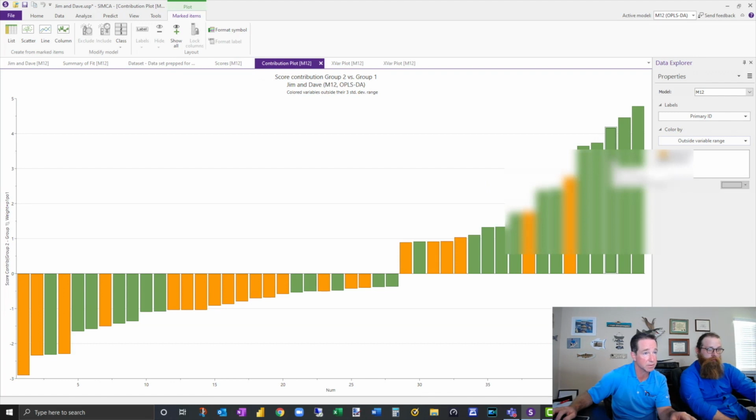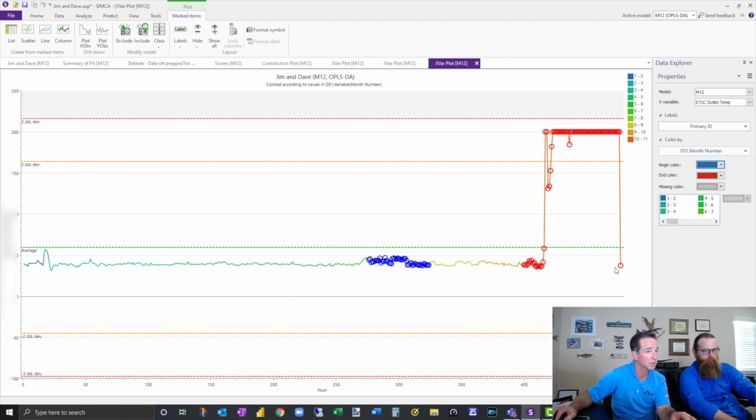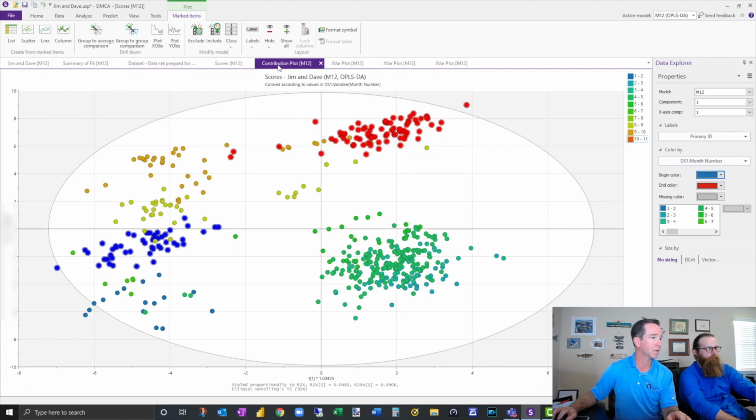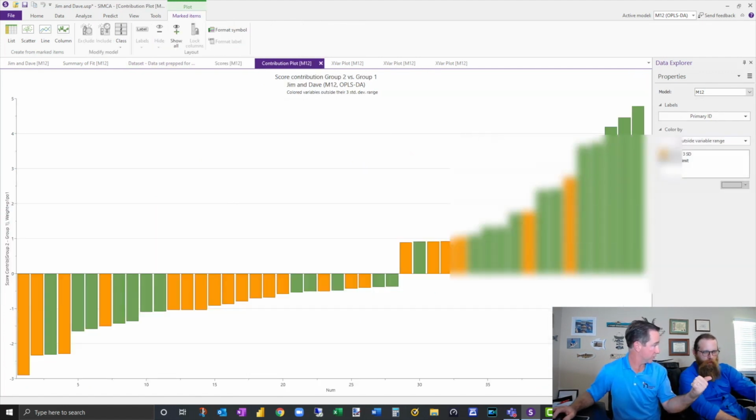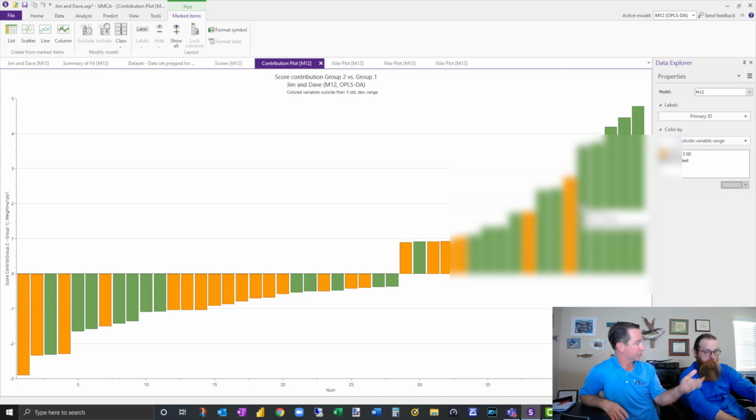Let's see, what was this one? That was another color one. The cycle number has nothing to do with it. Okay, there's an outlet temperature. Lost the sensor. You can see a flat line because we were about the same. Sensor problem. Could probably eliminate that one, because that sensor's been pretty stable all year long. So that's probably not a problem. But you can see why it contributed. So this is one of these correlation, not causation kind of things.